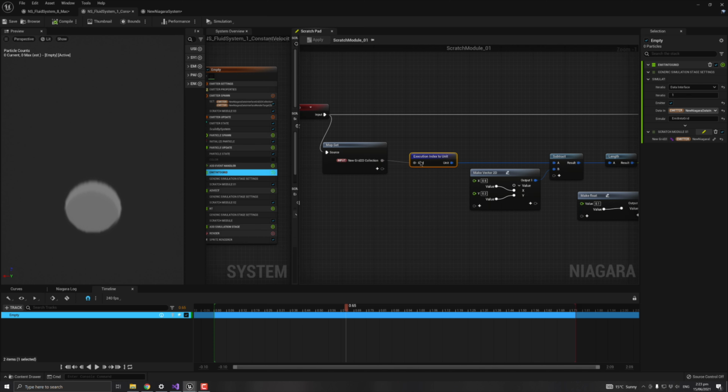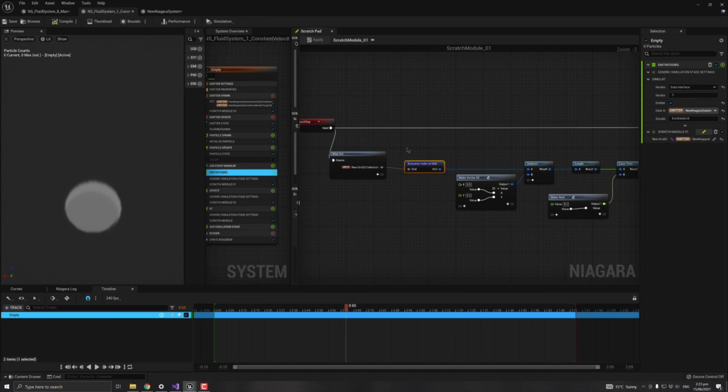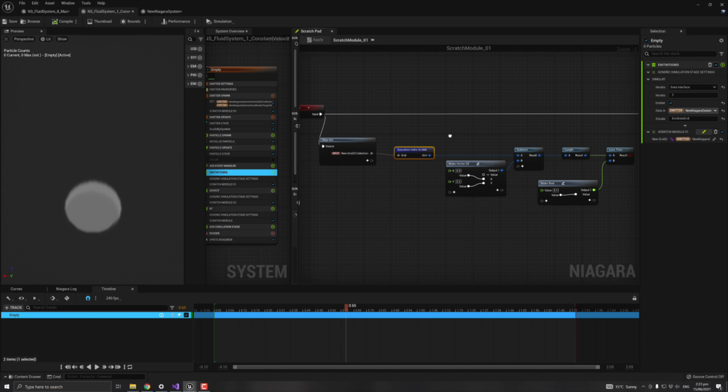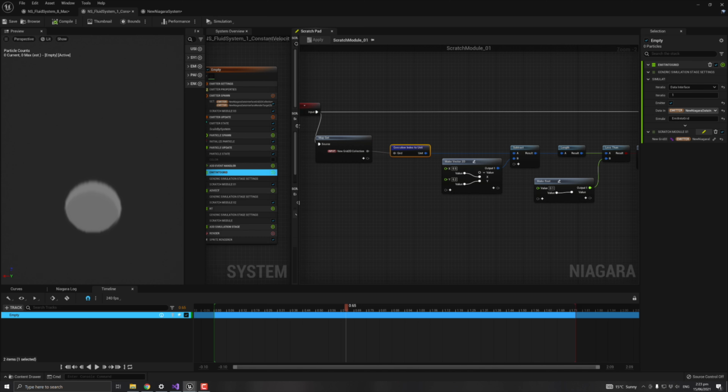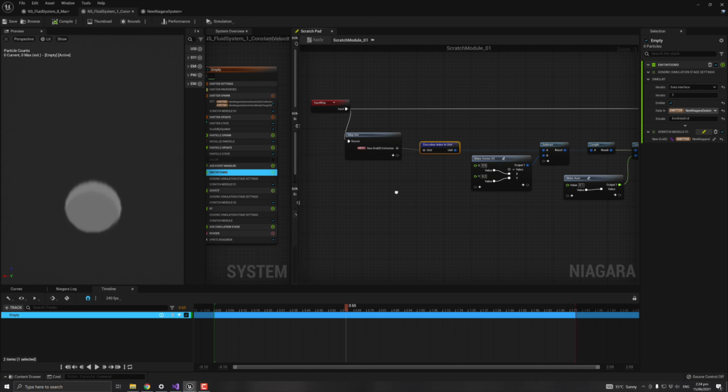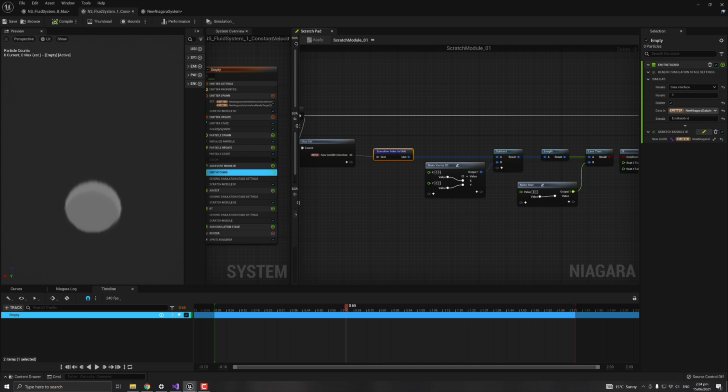Typically, when you run a module, it's basically a compute shader where each element of the thing you're operating on, whether it's particles or grids, which in the case of grids would be voxels, gets its own thread. So they all run in parallel. Each module runs once per element, and they all have their own execution index. The hardware is free to submit the work to the GPU in any way it wants, but ultimately they all have their own unique thread index.